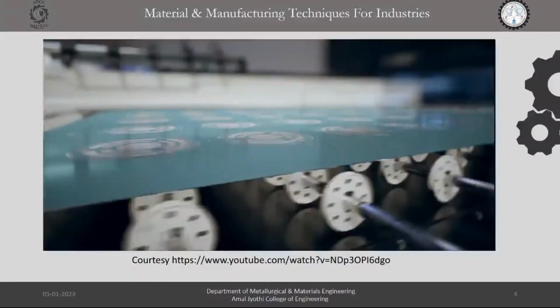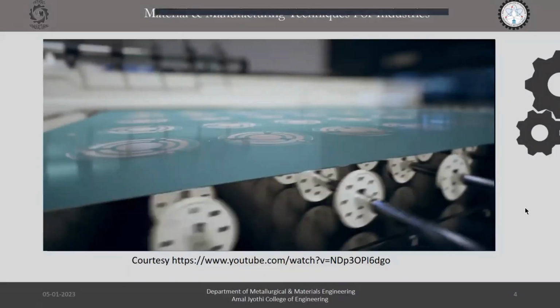What is the need for this cleaning? Why should we clean the workpiece? This is because improper cleaning could result in poor adhesion of the maskant, inaccurate final dimensions, and improper dissolution of the metal. Other contaminants like oil, grease, etc., can lead to oxidation of the workpiece.